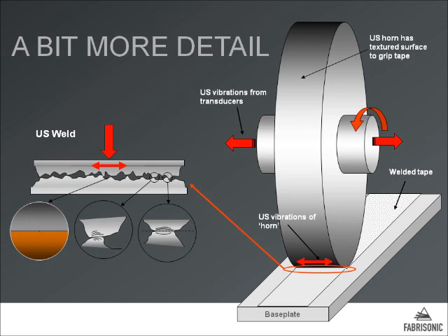It takes the ridges and valleys and rubs them together and actually rubs that oxide layer off. It breaks it up into small tiny pieces, exposing virgin metal on virgin metal. Because we're providing just a little bit of temperature and a little bit of pressure, we get a solid state bond between those two materials.